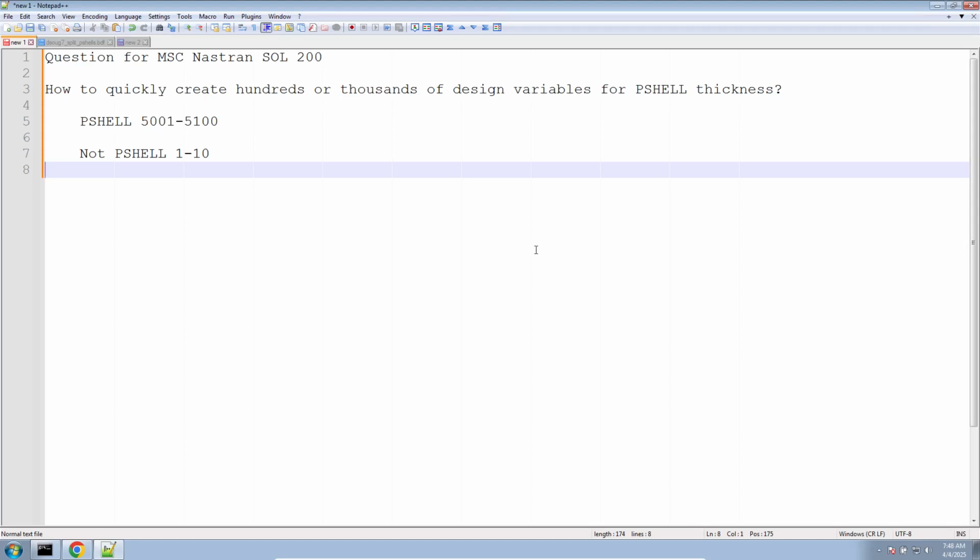In this video, we are going to go over the following question. How do I quickly create hundreds or thousands of desired variables for P-shell thicknesses? This might come up when you're trying to prepare an optimization for MSC Nastran SOL 200.